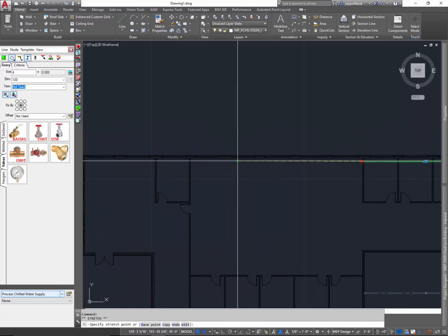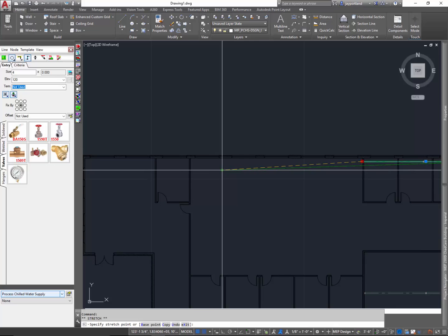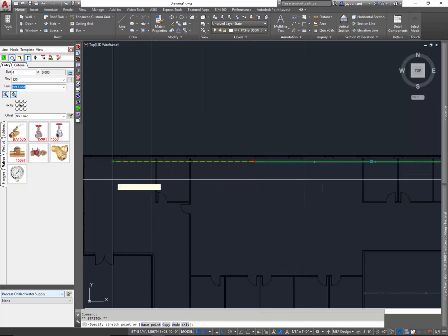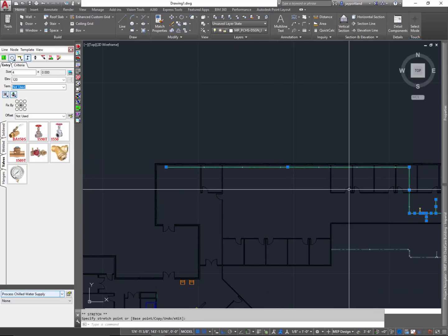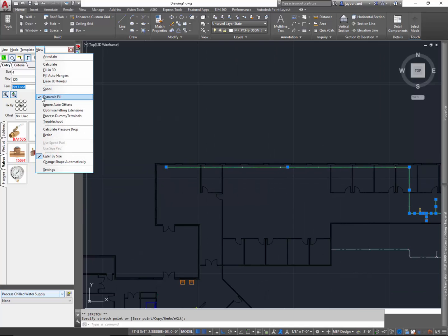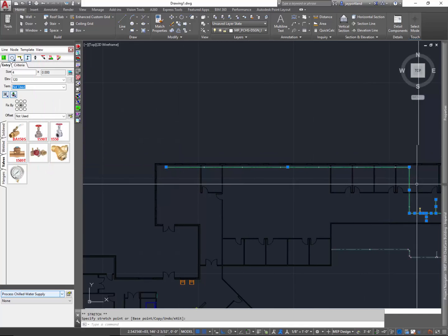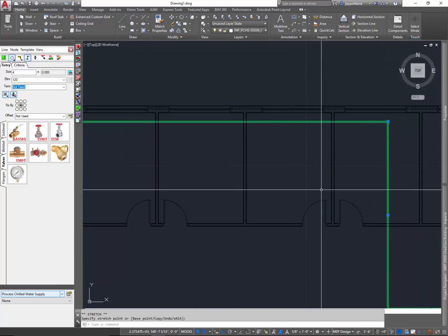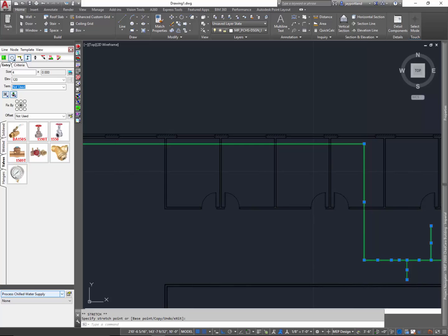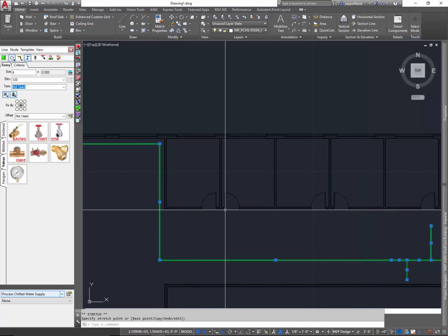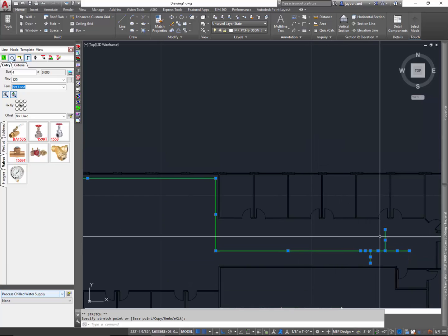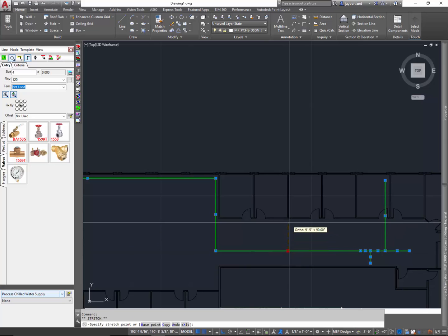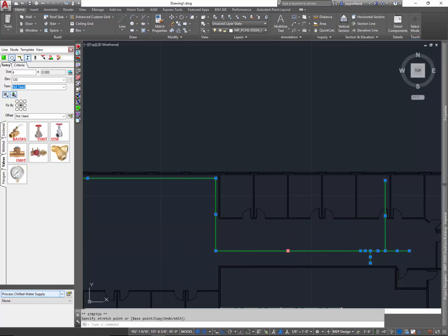So here you're seeing me make some movements here. All right, let's go ahead and pull this all the way through to the other end of the building. And I want to turn one quick thing off. I've got the dynamic fill turned on. So every time I make a move with the design line, it's dynamically filling that. So I can just press and pull. Once I turn that off, it's only going to give me the design line itself. So let's go ahead and start making these moves here so that it's tucked up real nicely up against the wall here.